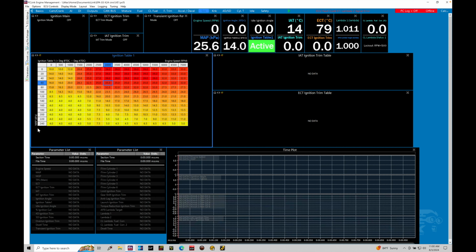It can be based on throttle position if you're doing an alpha-N tune, or it could be based on MGP, manifold gauge pressure, as we find our main fuel table is typically set up for MGP. MAP pressure is completely acceptable for setting up and working with our spark timing, and you'll find most base files from Link will have the main spark timing table set up as MAP pressure based. Regardless, it doesn't really matter in terms of the axes right now because, again, we're focused on the table values. But just note that the table here is set up MAP pressure versus engine speed.